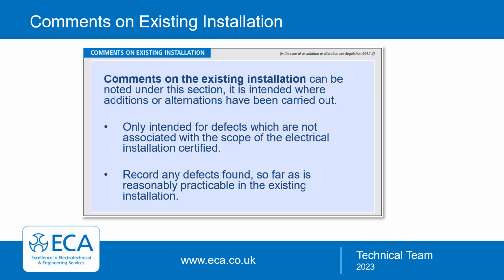The ability to make comments on existing installation is new for BS 7671 Amendment 2 and gives the opportunity to document any defects in the installation which are outside the scope of works you're completing. An example would be if a consumer unit or distribution board was being replaced in one part of the installation and there was a defect you noticed not associated with these works in another part of the installation. You only need to record what is reasonably practicable.